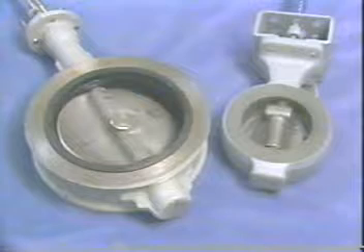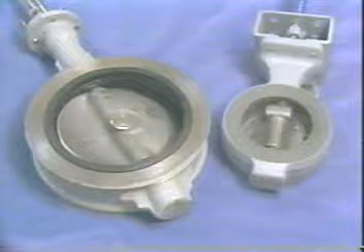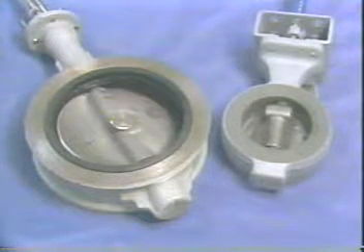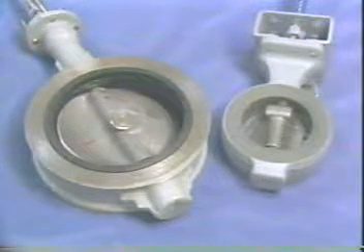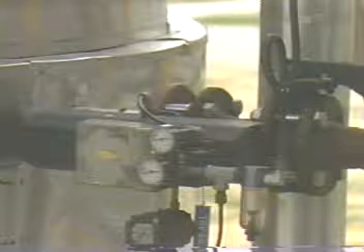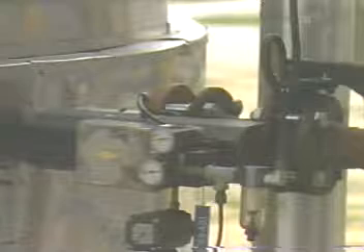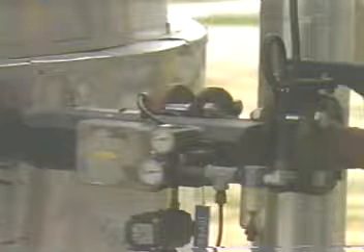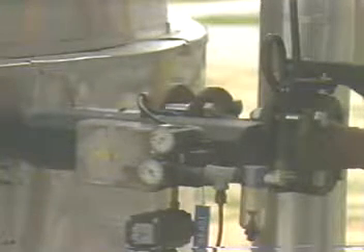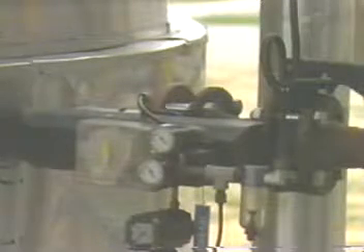A wafer body allows the valve to fit between piping flanges like a sandwich. A seal ring may be provided in order to obtain leak-tight sealing. Disc and stem orientation may vary as well, usually to obtain a better torque relationship with the actuator. As with any valve, there are problems you need to be aware of when making a selection. Because of its design, cavitation is more likely to occur in a butterfly valve than with some other valve designs. And because it is fast-acting, there is the possibility of damage due to water hammer when used in a liquid service. Another common rotary valve is the ball valve.